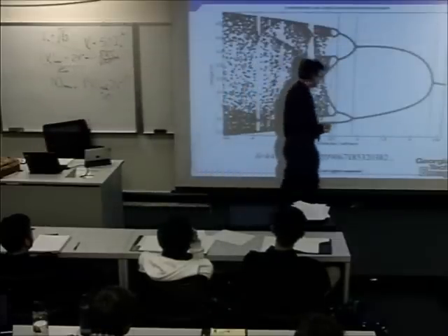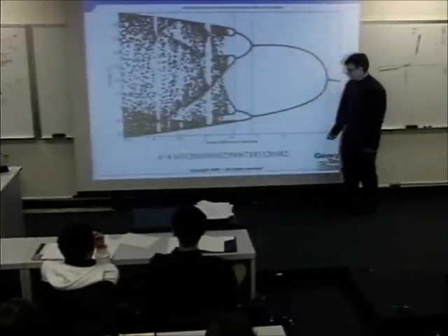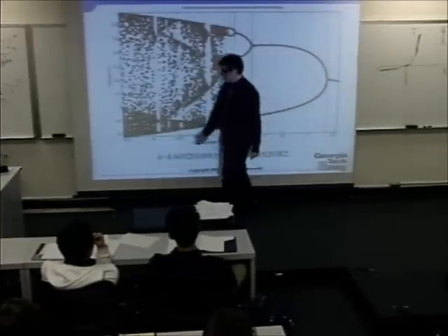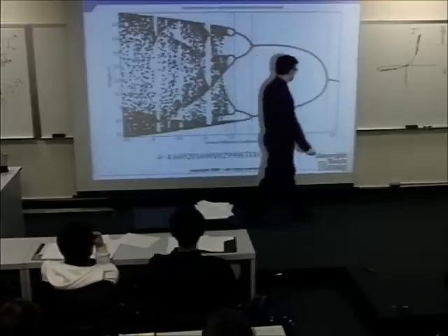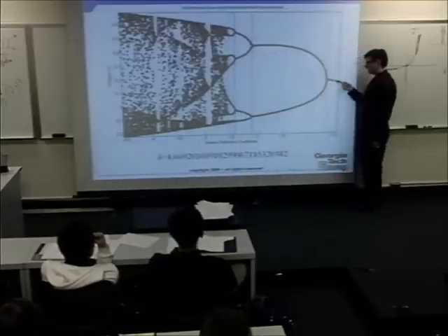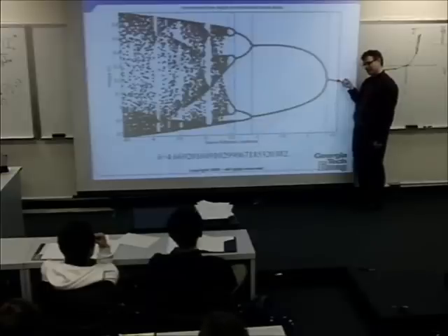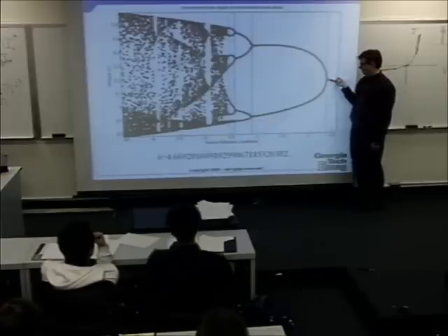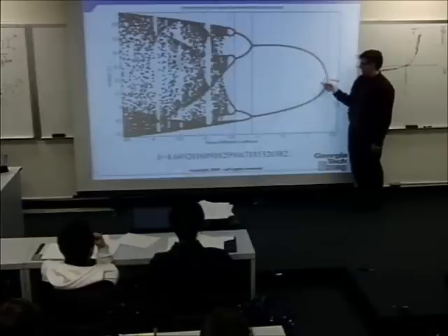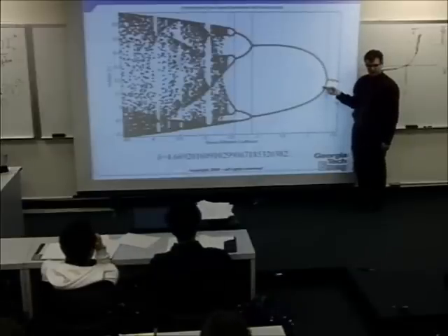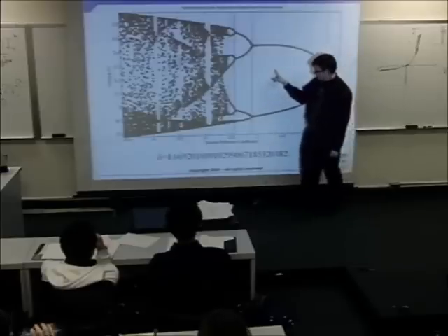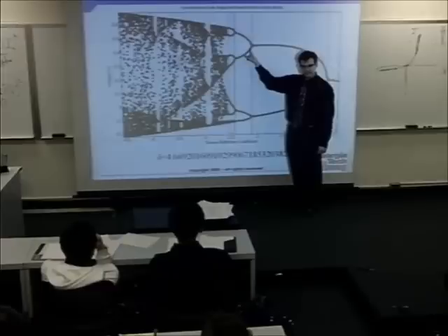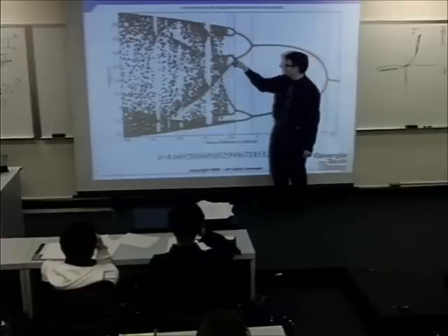So what I've done here is I've swept the resistance values, and here's the reflection coefficient on the source side. And here's the collection of output amplitudes of voltage I get from my circuit. Here's the part where I had a low positive resistance, and I was just getting one steady state. And as I lowered the resistance value to like 5 ohms, this is called a bifurcation. And that means that now there are 2 stable points that it oscillates between. And then as you keep going down, there's another point where it bifurcates again, and again, and again.